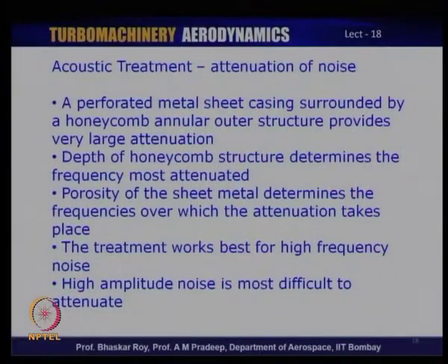The noise attenuation, or acoustic treatment as it is called in engineering terminology, is normally done with the help of perforated metal sheets with a certain perforation or porosity level prescribed by the designer, and it surrounds the compressor or fan.